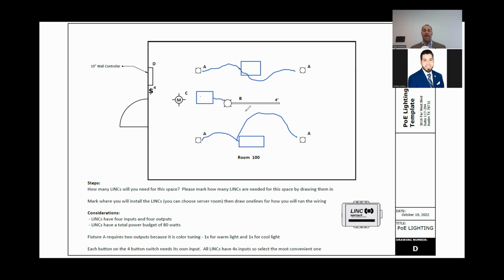We don't recommend, that's a good question. We don't recommend running any constant current light fixtures in series. We definitely don't recommend running more than 2 in series if you really feel like you've got to do that.